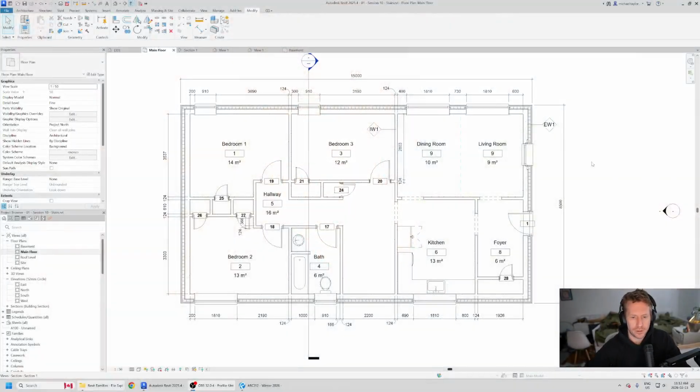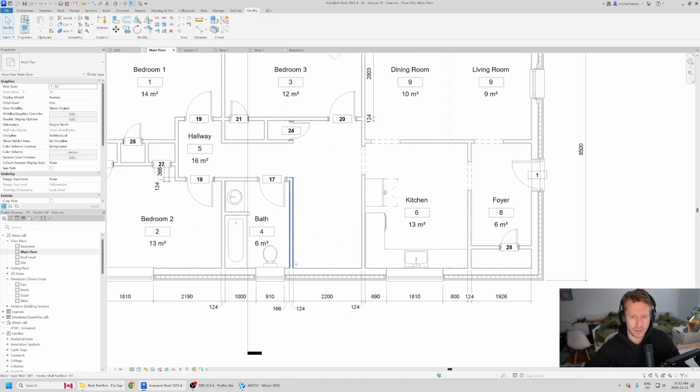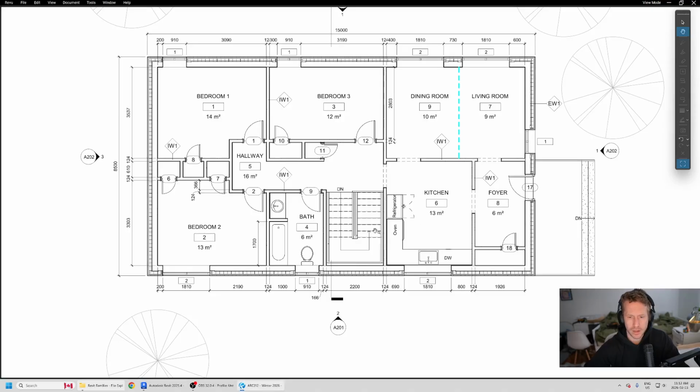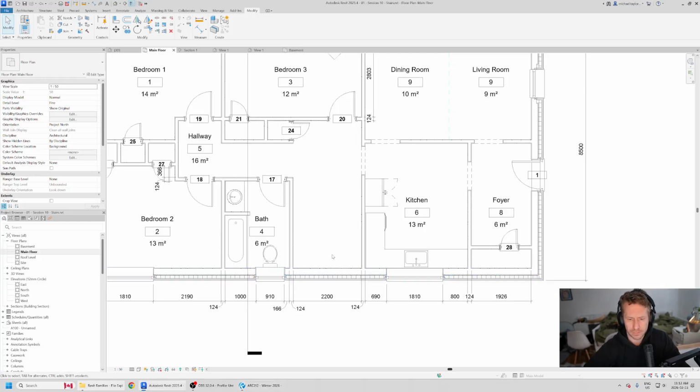Where we left off was getting some of these components into our drawings, right? So we've got a location for where the stair might go. It's going to hang out right here. So if we go to our reference drawings, there's our stair. Provided you've used the architectural template from Blackboard to start, you should have this stair family inside of your Revit project. So first things first, we got to cut a hole.